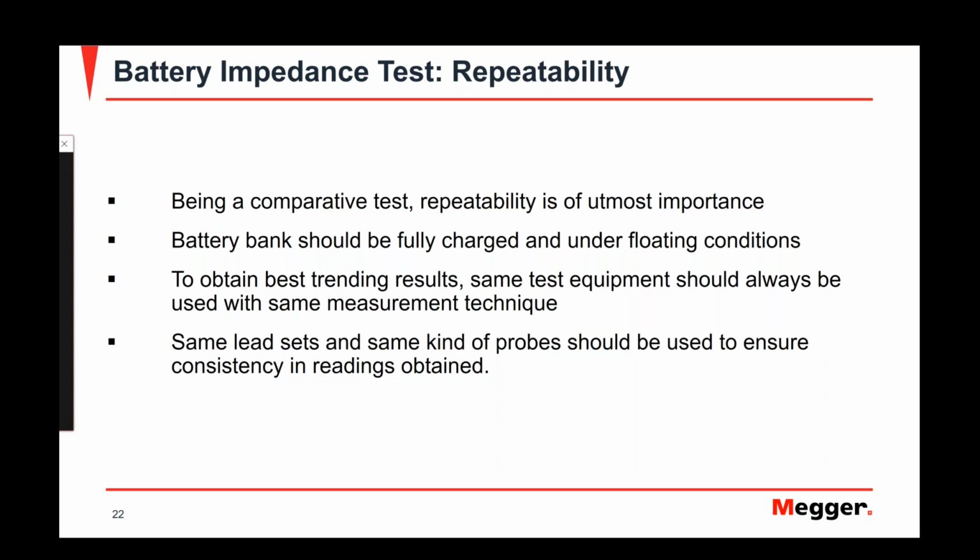A couple of things that are recommended: one, the battery string must be in a fully charged state, and it also must be in a float condition every time that we take these measurements. We'll take a deeper look into that later in our discussion about how to do that.